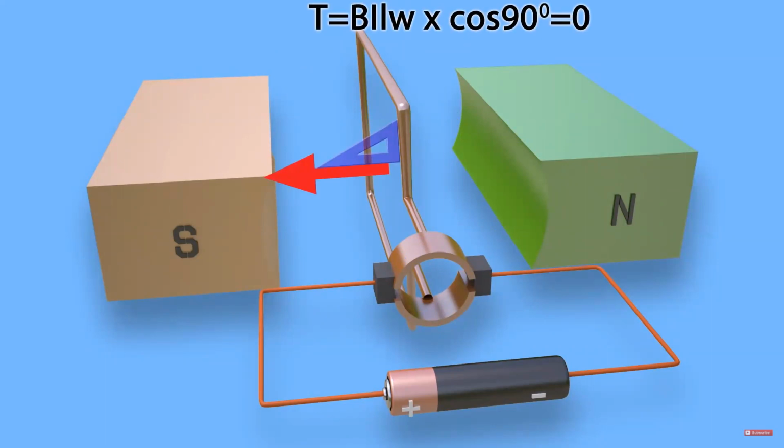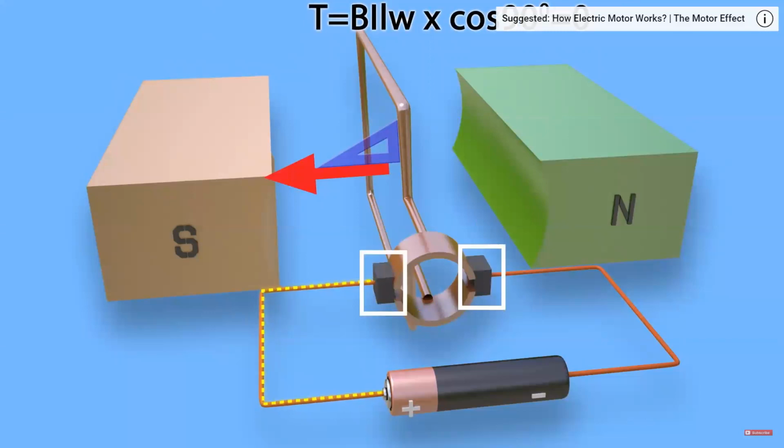After rotation, the turn comes to a vertical position with respect to the magnetic field. At this position, there is no current in the conductor because the turn, conductor, and brushes rest between two commutator segments.